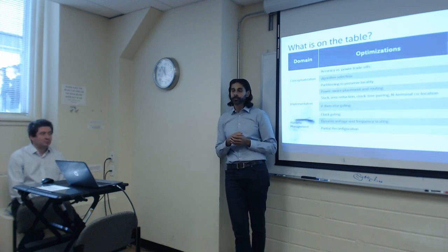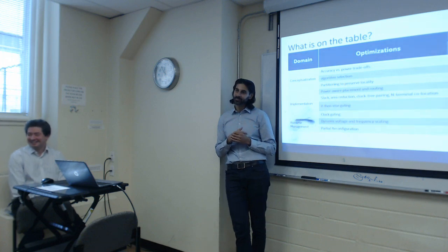Okay, now I remember my question. You're calculating junction temperature across the die with a 2D thermal model, I guess. What use are you making of that? Are you using that to check for hotspots and say you've got a problem, or are you also using it to calculate static power, where you're taking into account local temperature gradients?